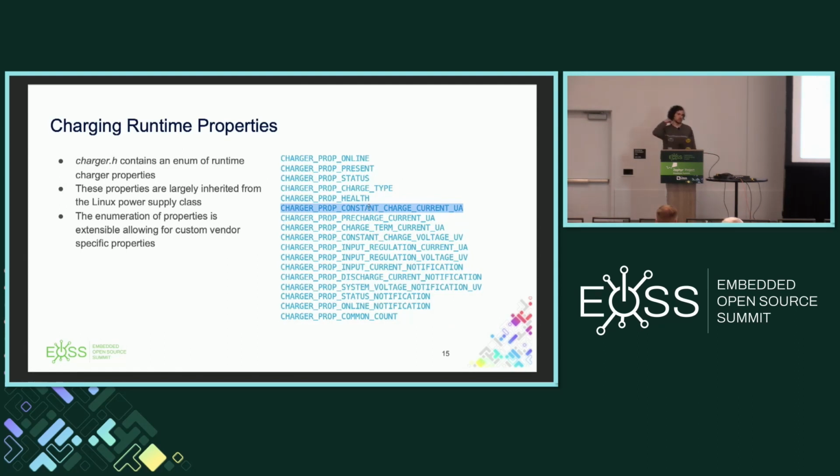So you would want to reduce for health reasons? It's actually the capacity rather than the charging current. So say limited to 85% of the full capacity of the battery. So you would have to do that math on your own. Okay. Yeah. Okay. All right. Thank you.